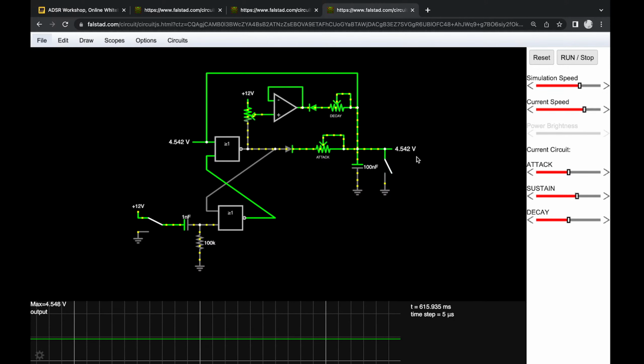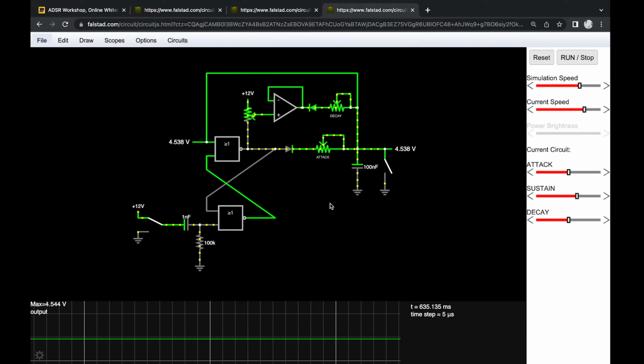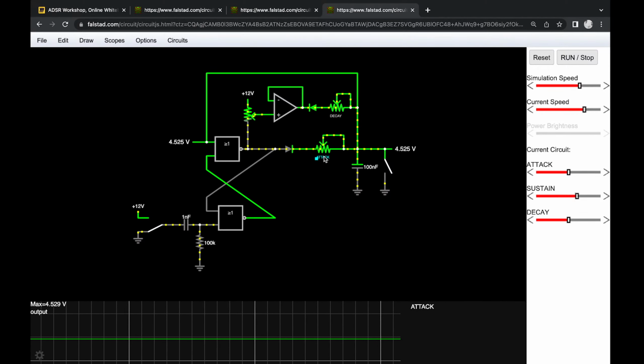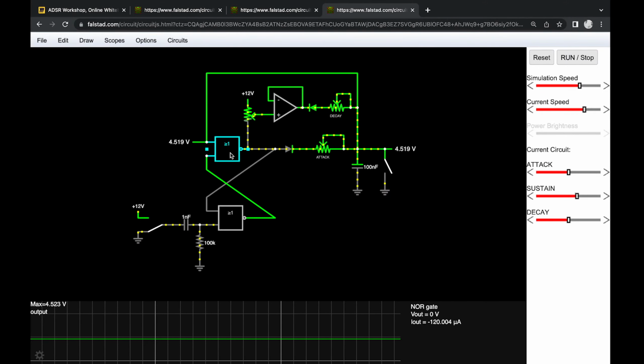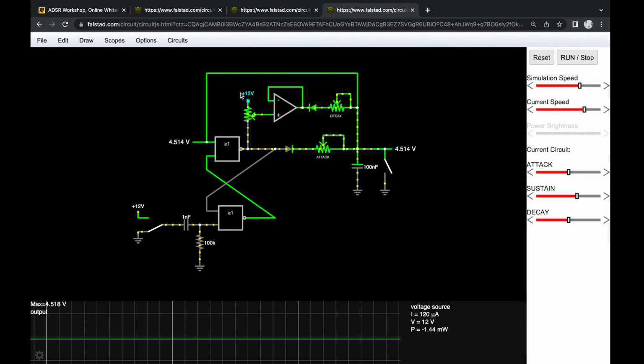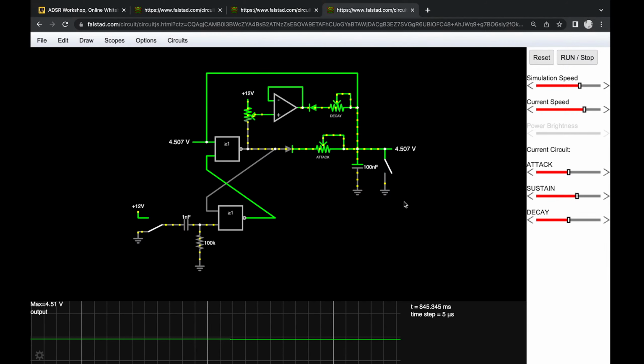Right now we're effectively at the sustain level. Right, and even if I let go of the key now, nothing happens because we haven't implemented the release. But yeah, with this little addition, we already have the decay and the sustain phase. So sustain is this potentiometer, and decay is this potentiometer. That's it. That's all we need for that.